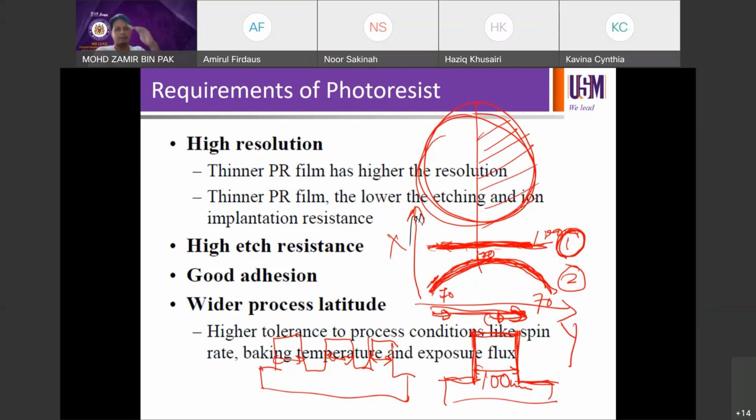If you target 100 nanometer plus minus 3 nanometer, then suddenly your CD gets to be 105 or 96. If the target is 100 nanometer plus minus 3 nanometer, that means your CD can only fluctuate between 97 to 103 to be considered okay in spec. If you suddenly see 96, which is on the lower side, or 105, which is on the higher side, it has already fallen out of spec, something is happening. So we call that CD drift.